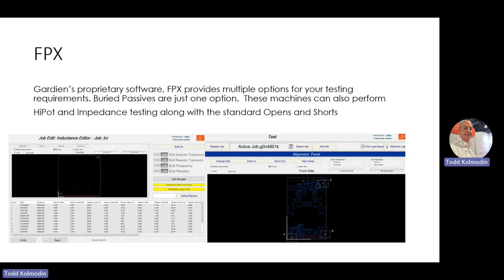And it'll print out a tag if you so desire, and it also logs that as a report option in the system. So you can actually go back and read the values, see where adjustments might be made, or see where maybe a systemic fault is happening, or you're seeing an entire array of the resistors all low or all high. Maybe there was an etching problem, something like that. But that's all available to the operator or design engineer.